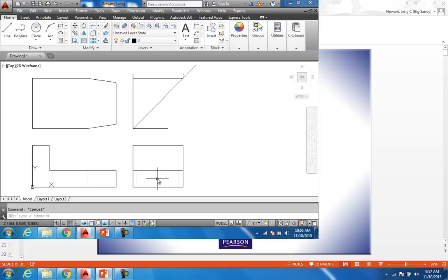Now, what I want to do is put this little groove in here, and to do that, I want to do it on the top view. It's going to offset 2.25 enter. We're going to jump back right off that one. Line, catch that center point. I want to bring it back. So right there is my center point to put a 1 inch diameter in.